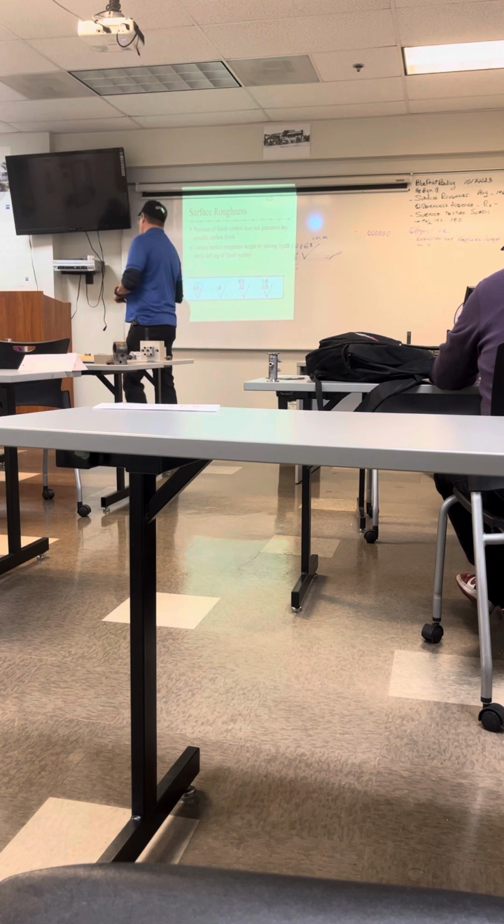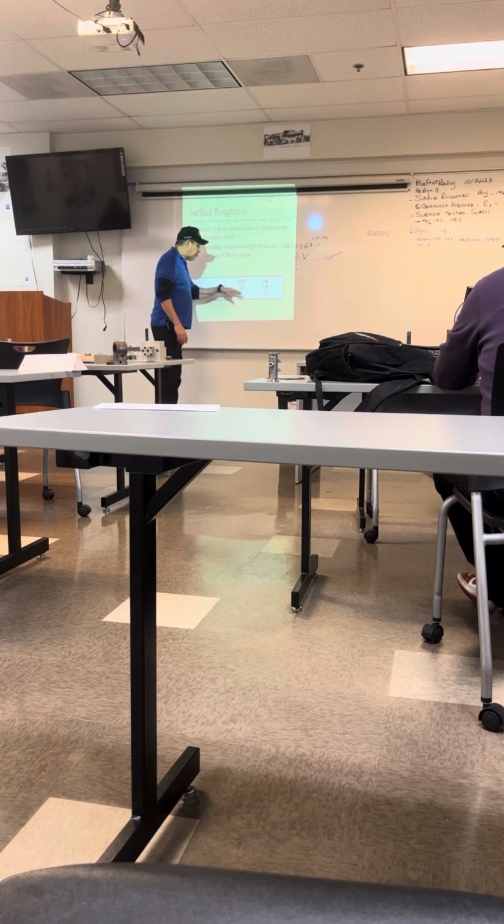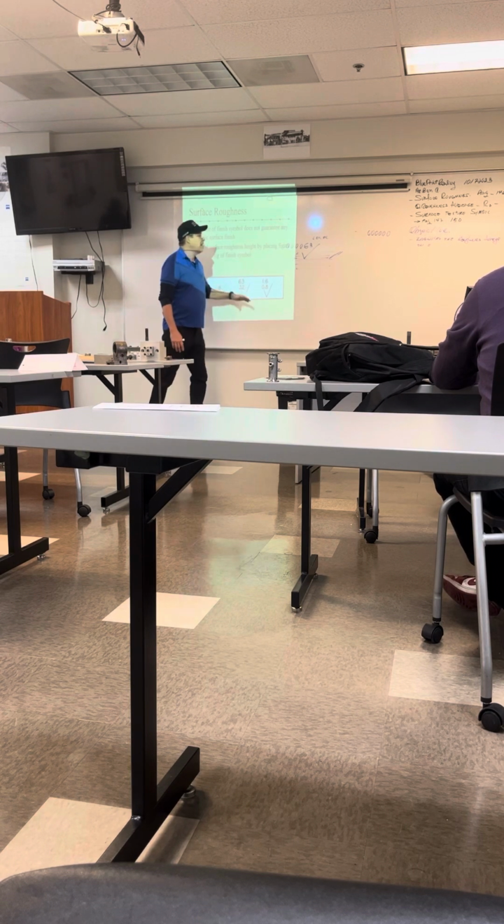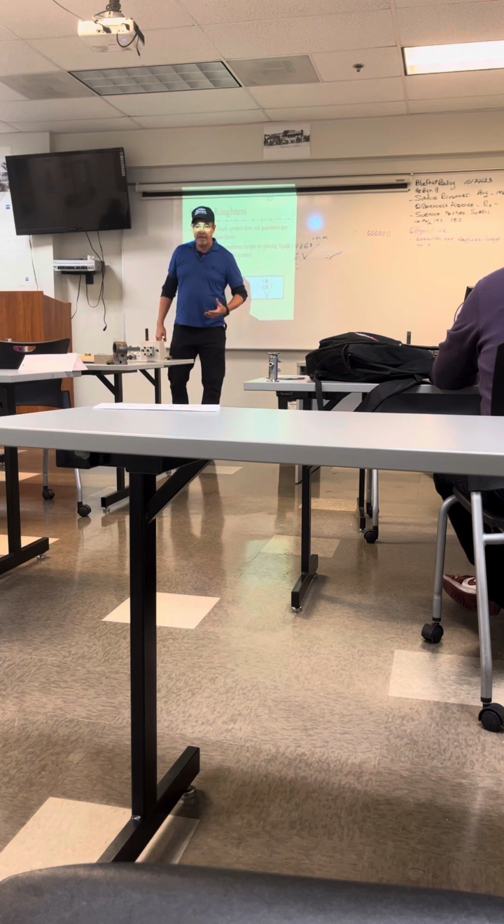So we take 63 millionths or 32 millionths of an inch, because an inch is a little bigger. But in a meter, we have, I don't know, like 39 inches, something like that. So they take one only, but it's almost the same amount. Does that make sense? Yes. So that indicates the amount of roughness on the part.